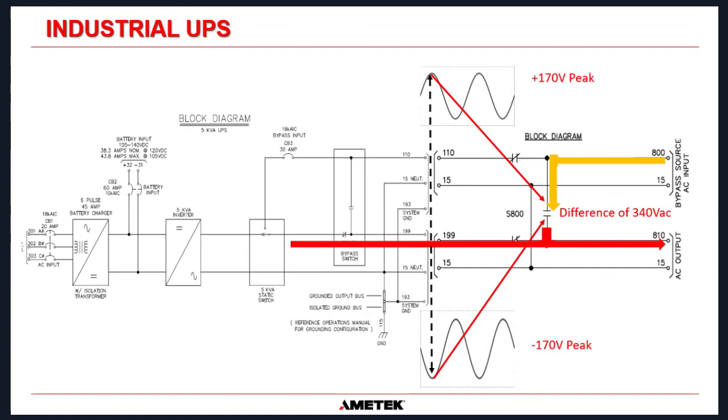And that's going to cause usually damage to the inverter bridge. And that high current, if you think about it, is probably going to cause the bypass source to trip upstream at the MCC because there's uncontrolled high current. And if you've moved that switch from normal to bypass, then the switch is in bypass position now. And if the bypass breaker upstream at the MCC trips, then that means you've lost power to your load circuits.